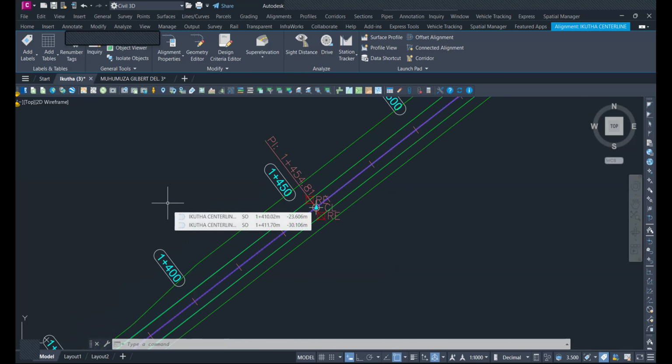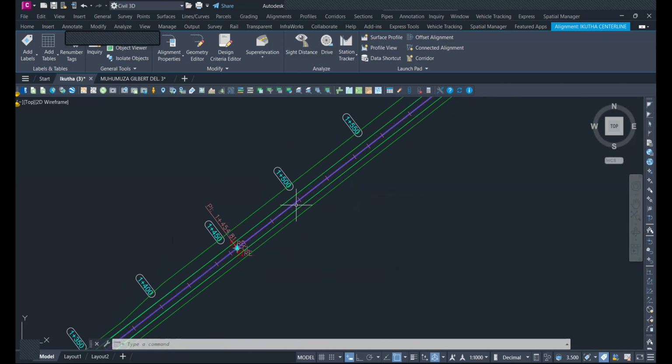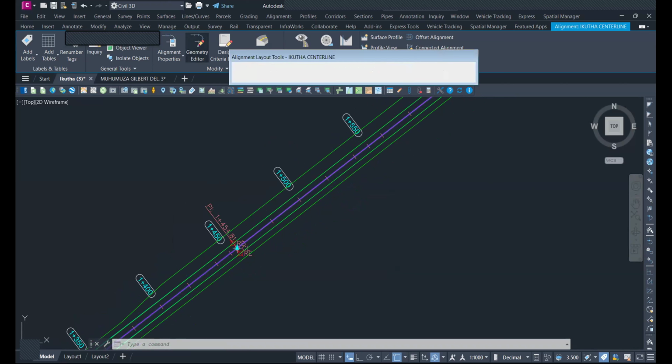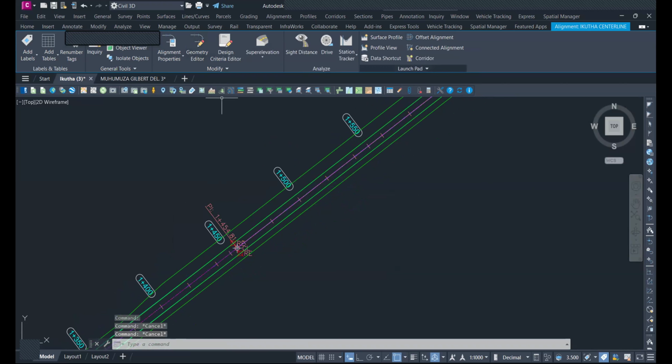Okay. I expect that, and that's a good way of getting the work done. But when we look at it from a technical perspective, this brings a disjointed section, so we consider it non-continuous. And of course, in road design, the alignment should be very continuous. So yes, the PI helps you to create and achieve the alignment, but you can remove them after you do your design.